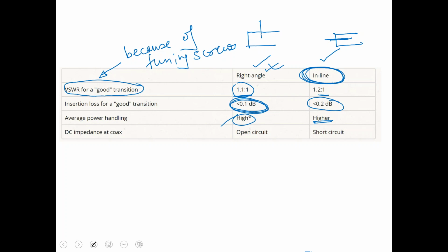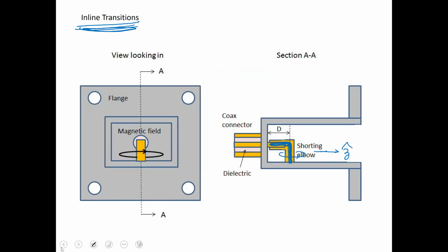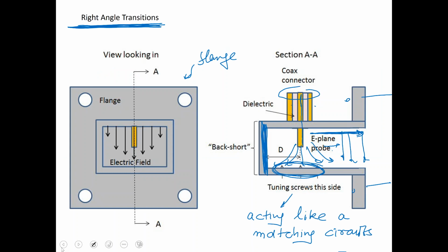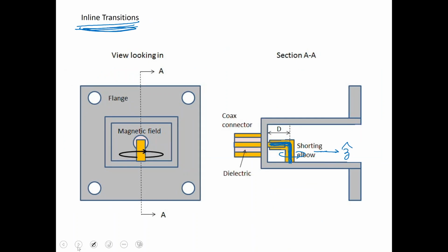Most of the power is transmitting forward, which makes life a bit easier and doesn't create hot spots around the metallic waveguide. Thus you can handle a lot more power before the waveguide becomes too hot because of the energy which could be collected in this region, any standing waves which would be created in that region.